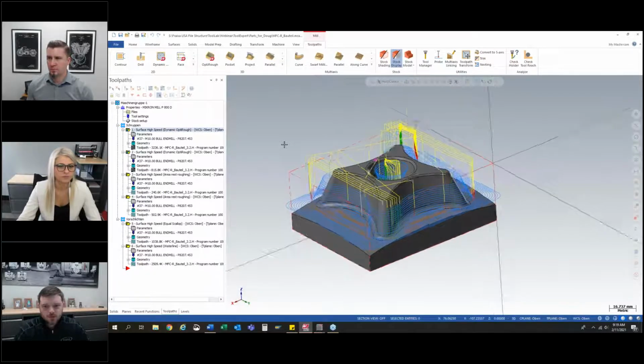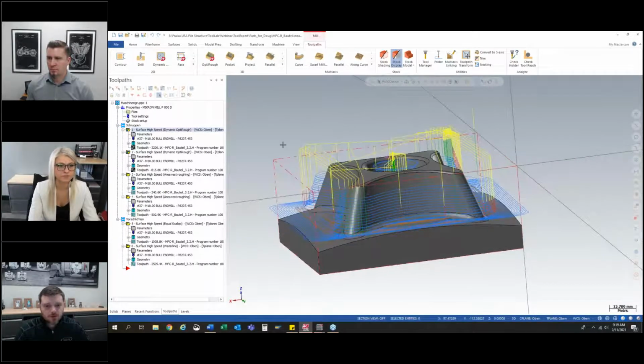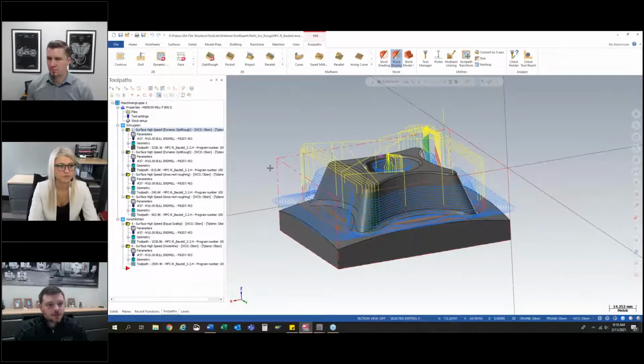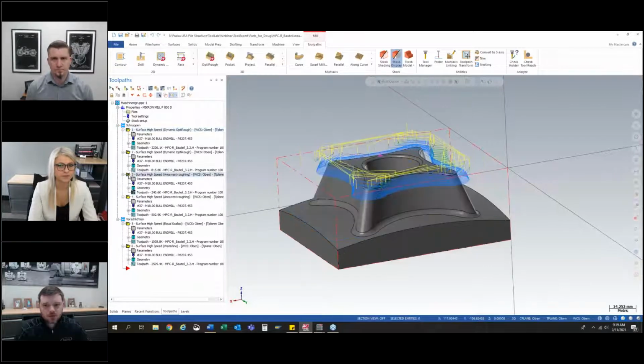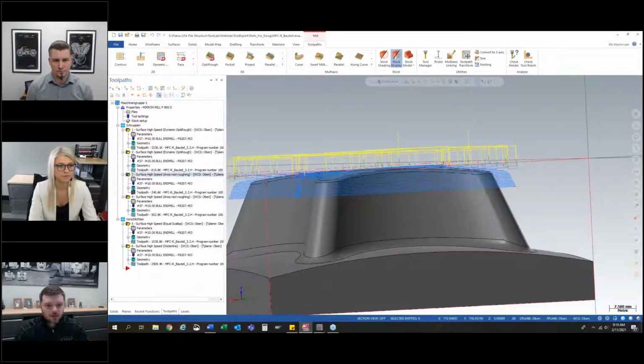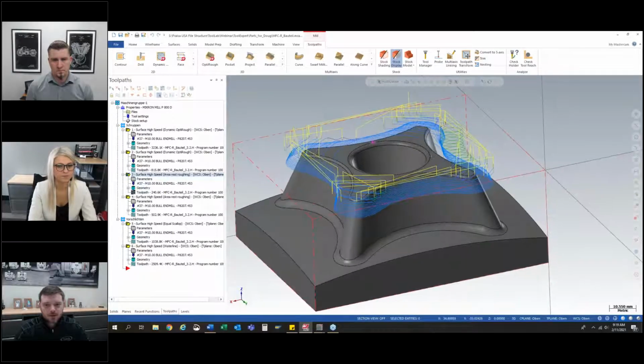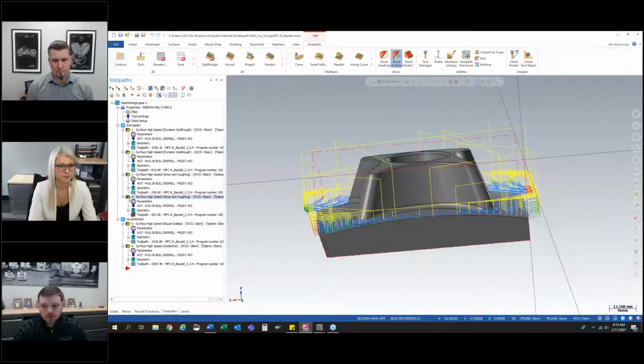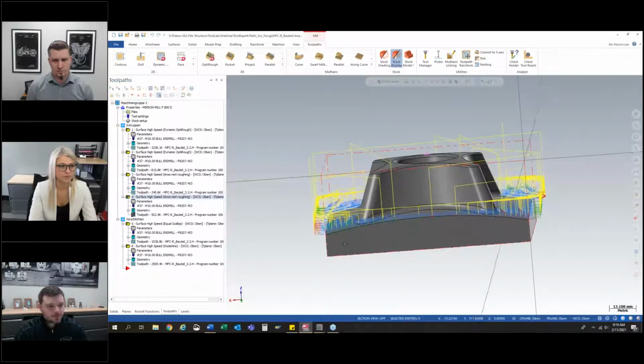So we start off, because all of these surfaces are tapered or curved, with Mastercam's OptiRough path. So it's a dynamic milling in and then bottom up roughing to the top. Then we switch over to a high feed type cut, because this is a very flat, low curvature surface at the top of it. So we're high feeding around the top of it to remove that material. Same thing for the lower portion, because it has that same curvature down here.